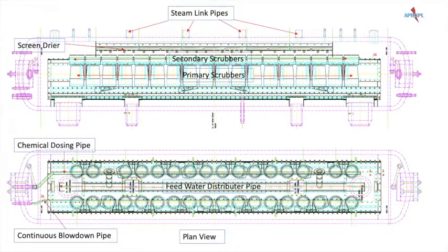Remove part of the water by blowing down to control the boiler water chemistry by dissolved solids content. Blowdown lines periodically or continuously remove a portion of water from the boiler. Sufficient high solids boiler water is removed and replaced by low concentration feed water to maintain a desired concentration in the boiler water. Provide limited water storage to accommodate rapid changes in boiler load.